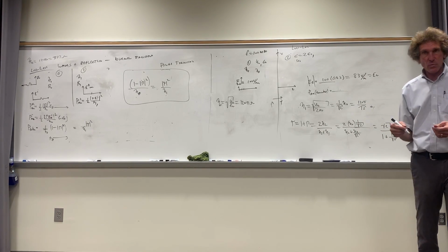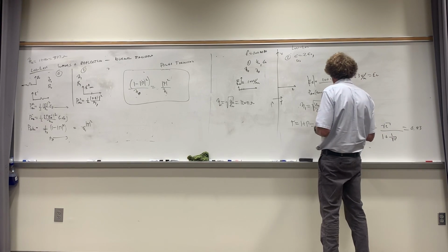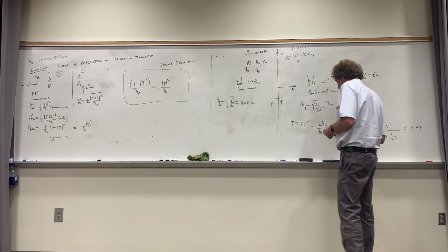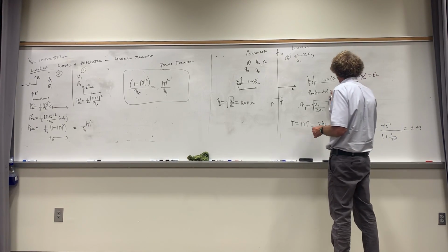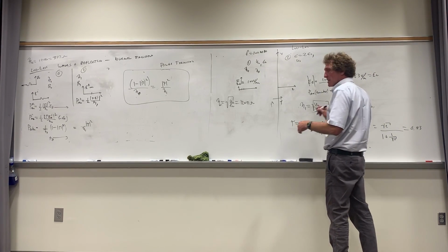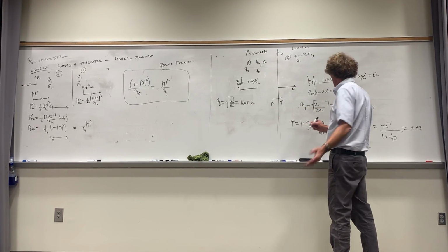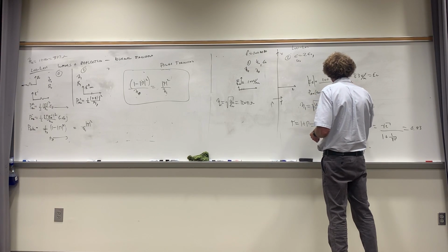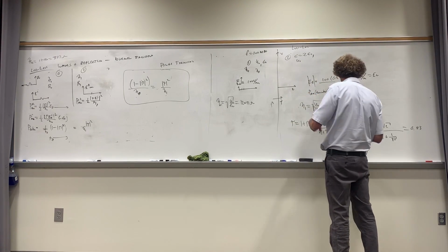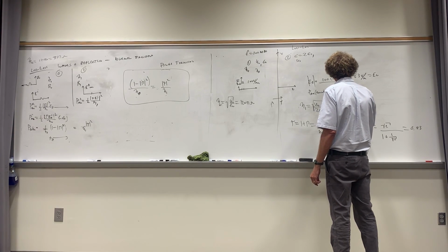All right, what's the power density transmitted? Now the average power transmitted. This is watts per meter squared. What do I need? It's lossless. What did I say this is going to be? 1/2, right, times the magnitude of the transmitted electric field, right, which is 83, squared, divided by eta in that region. Eta in that region is what? 120 pi divided by square root of 2, correct?